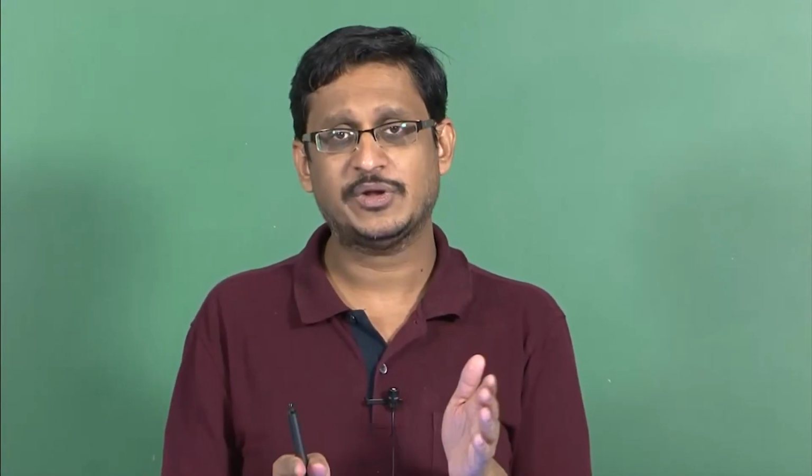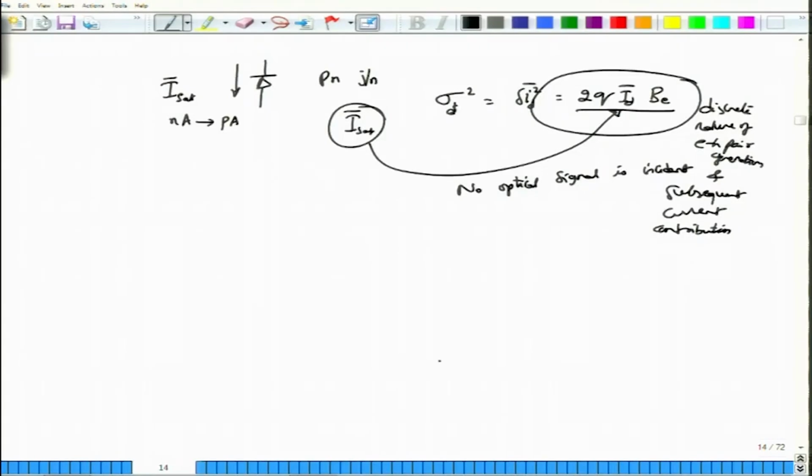So, there is shot noise because of the source, and there is shot noise because of the detector process itself. Usually when light is turned on, this detector shot noise can be neglected, but when light is turned off, the detector shot noise cannot be neglected, and that is the source of this expression 2q id bar BE, which is exactly the same expression as the input. In fact, in any shot noise situation, when there is any discreteness and you are doing a counting application, you would essentially encounter shot noise expressions in all these scenarios.